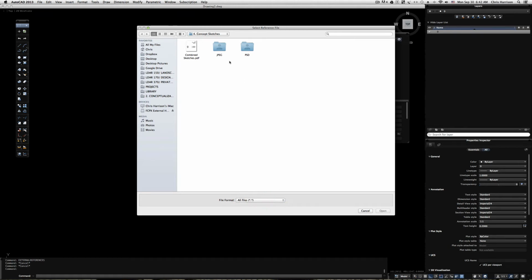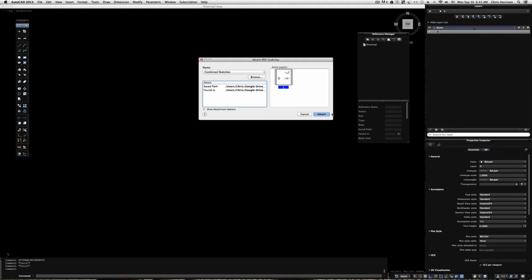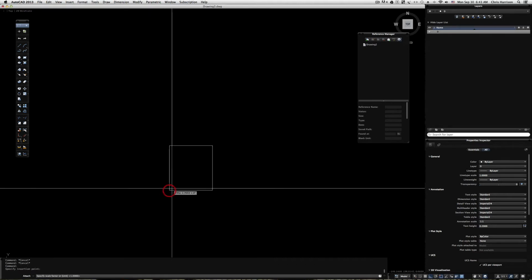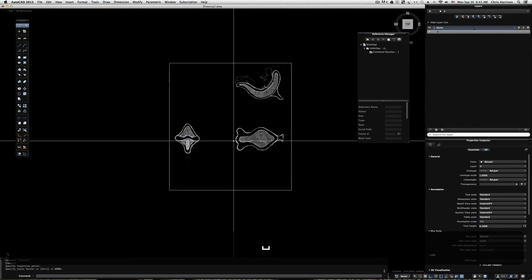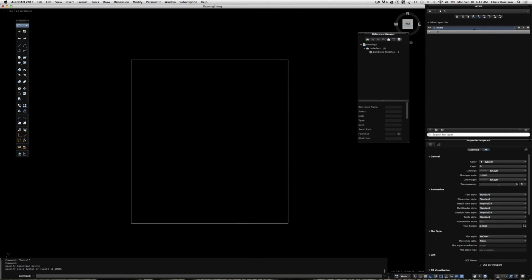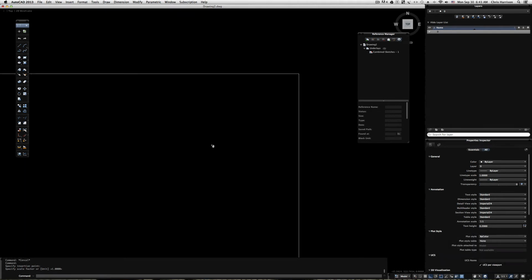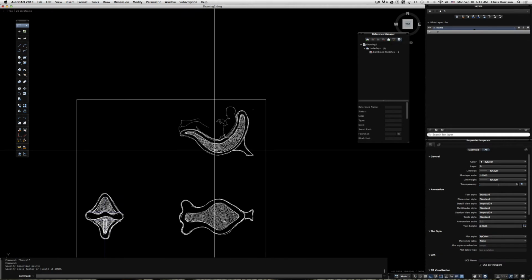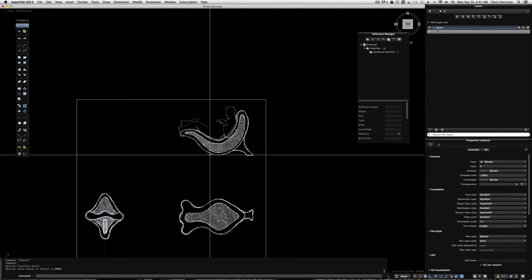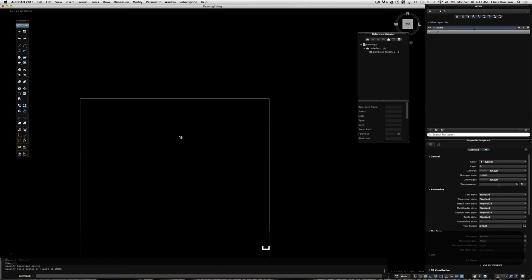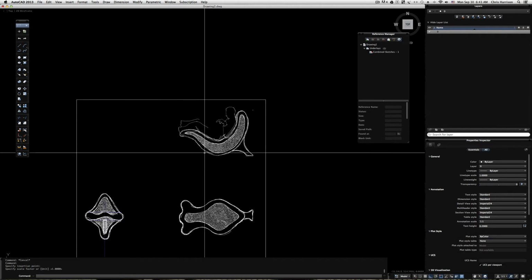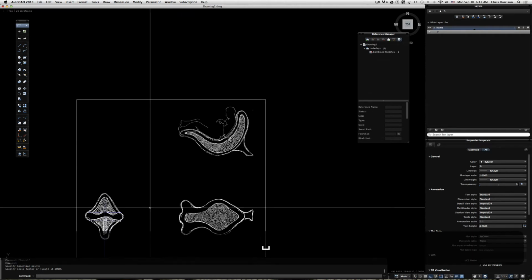I have all files selected for this one. I'm navigating to my combined sketched PDF. I'm going to select open. Something else worth mentioning is when you have images in, you might see some drags occur when I'm sketching over this. That's typical. Even though you're referencing an image, it can sometimes slow down your program. I find that PDF documents work a lot better than JPEGs typically to trace and go over.